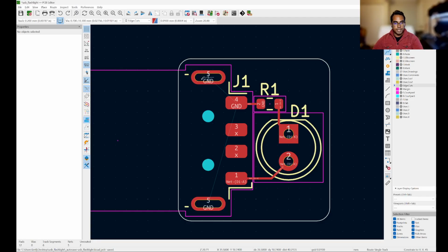two-layer boards like this with a large ground, is you can use a copper pour. You can use an entire filled area that connects to the ground instead of just a single thin line, and that ensures a more reliable connection to ground. It also prevents, or it absorbs stray electromagnetic radiation to keep interference from hindering the performance of your board.